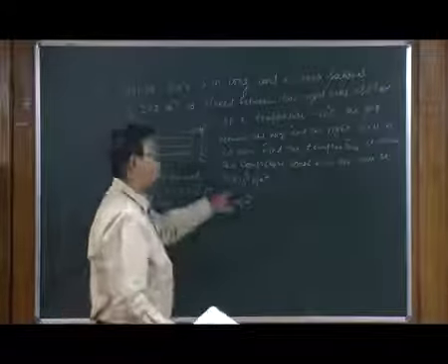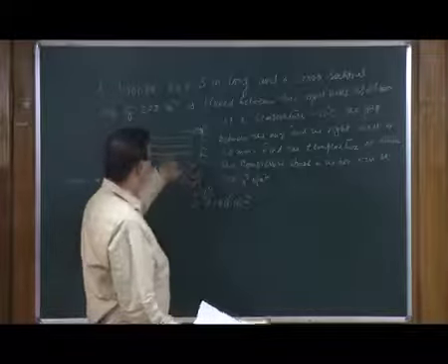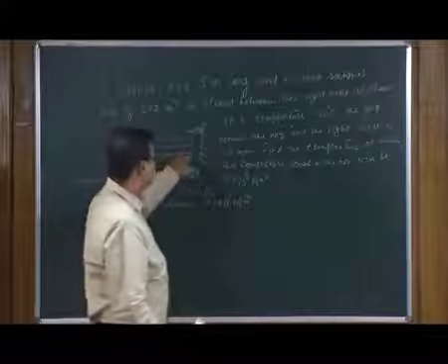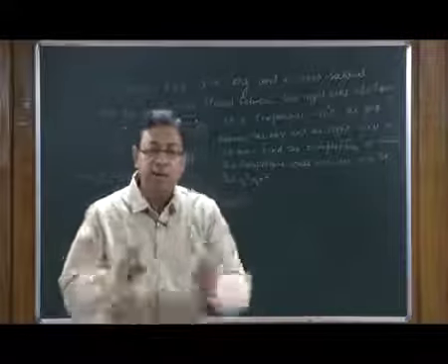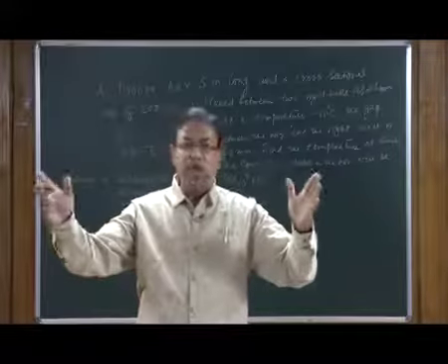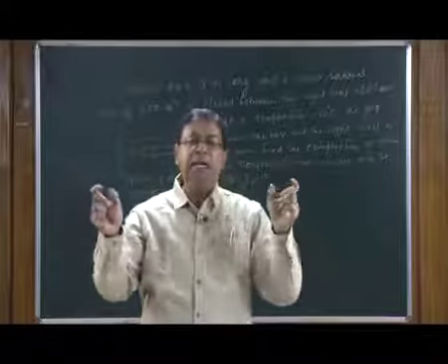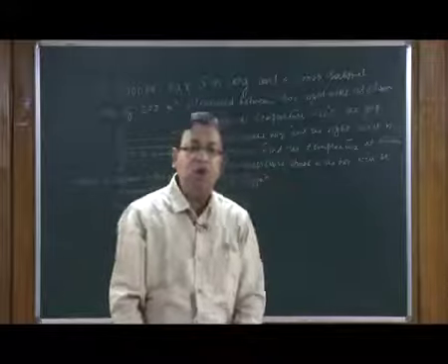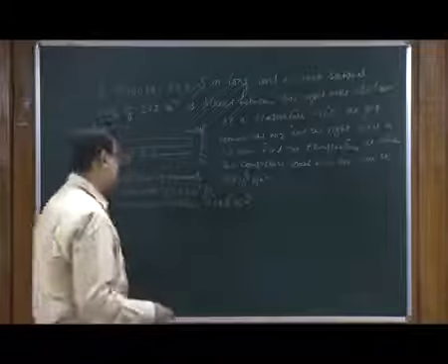So, at this situation there is no compressive stress, because the compressive stress will come when the bar touches the right wall and tries to extend farther. So, we have to find that extension because of which the compressive stress is developed.